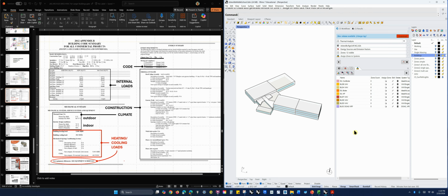So again, wow, that's interesting that these slides tie into the practical real world. Even the drawings we had were from Climate Studio, and we made the basic point that the VAV is heating, cooling, and fresh air all going through air. But with the DOAS, the direct outdoor air system, we're only bringing in fresh air. We're only moving air to bring in fresh air, and we're either bringing heat or cool with hot water with the FCU or with refrigerant with the VRF, variable refrigerant flow.